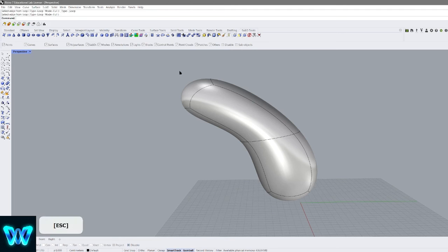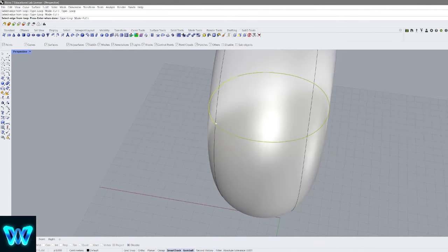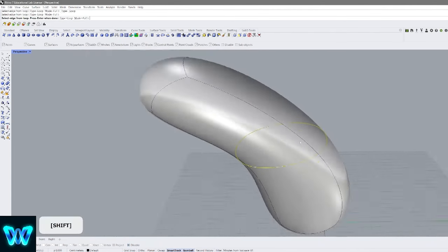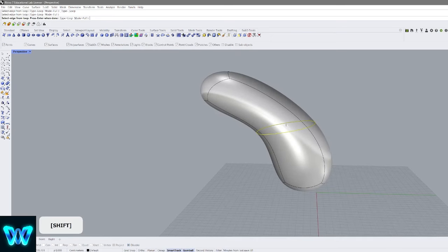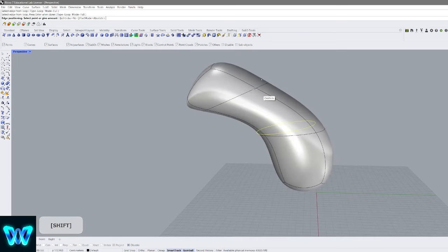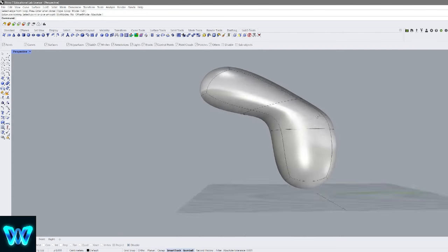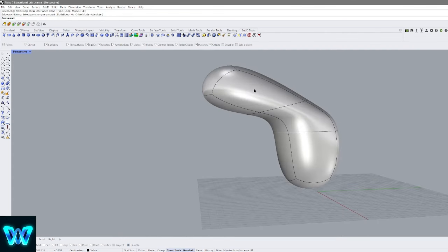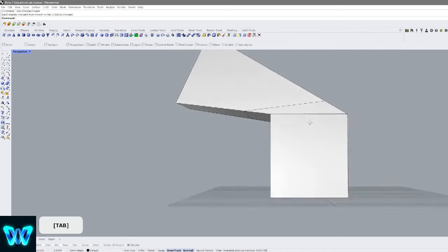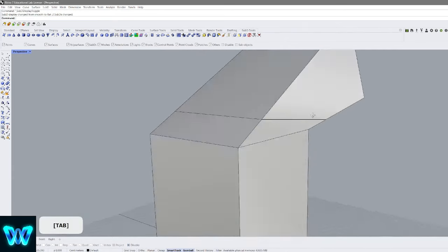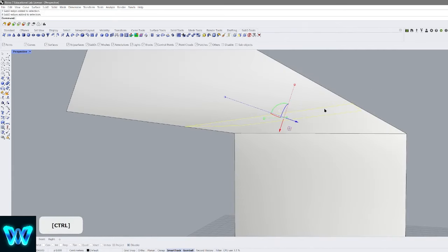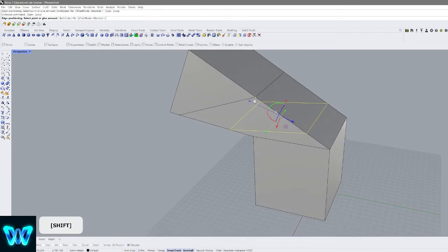So the way edge loop works, when you click it, you can select an edge loop. So this right here is an edge loop. It's a looping edge because they connect through all sides. The moment you select it and you click enter, now you can add an extra one, which adds detail pretty much. And when you add detail, you add more sharpness into your form. And if you look at it in polygonal mode, all it's doing is just adding a new curve.